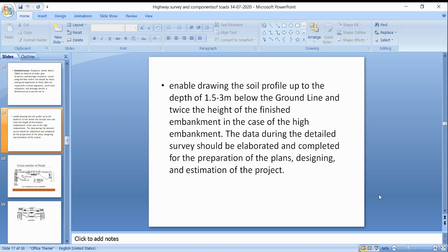For a road project, here we are following the chain and compass or theodolite. In the preliminary survey we have seen the level, the dumpy level, and the theodolite itself. Here we are finalizing with the total station or the theodolite for the fixing of the center lines, establishing benchmarks along the route, and finalizing the longitudinal sections and cross sections of the proposed routes.